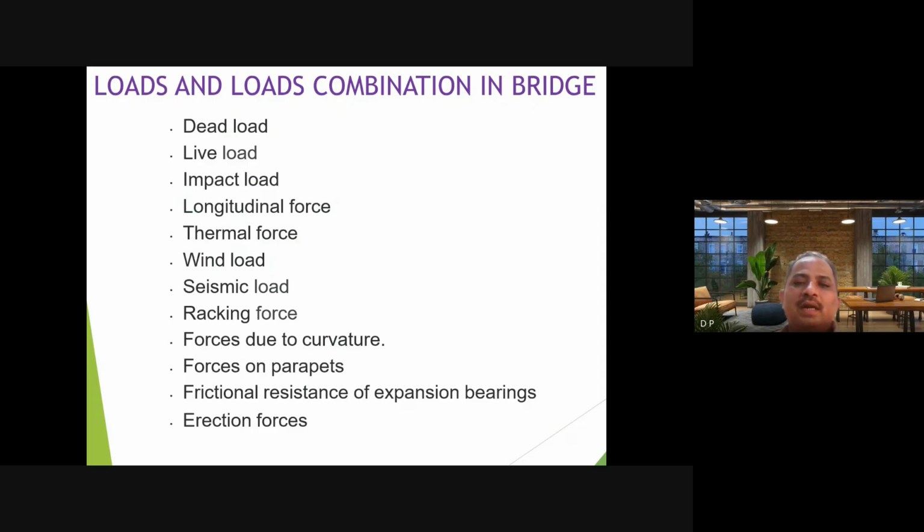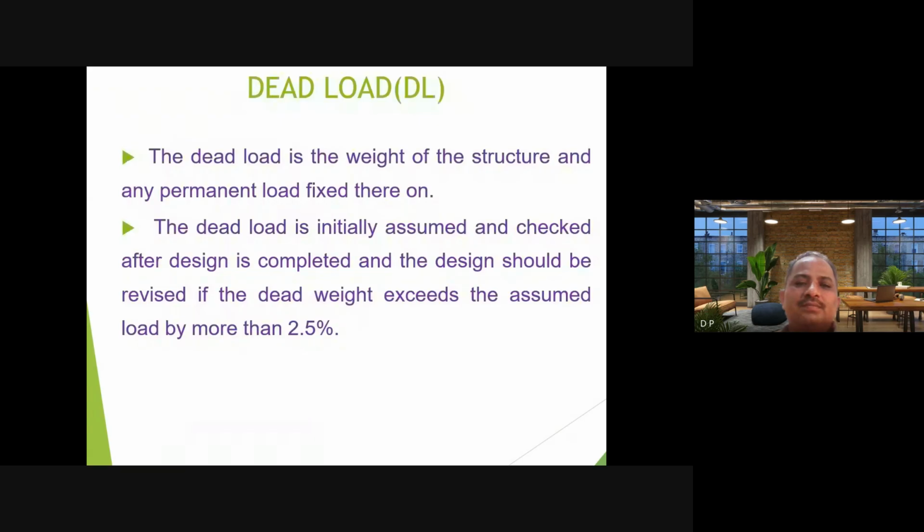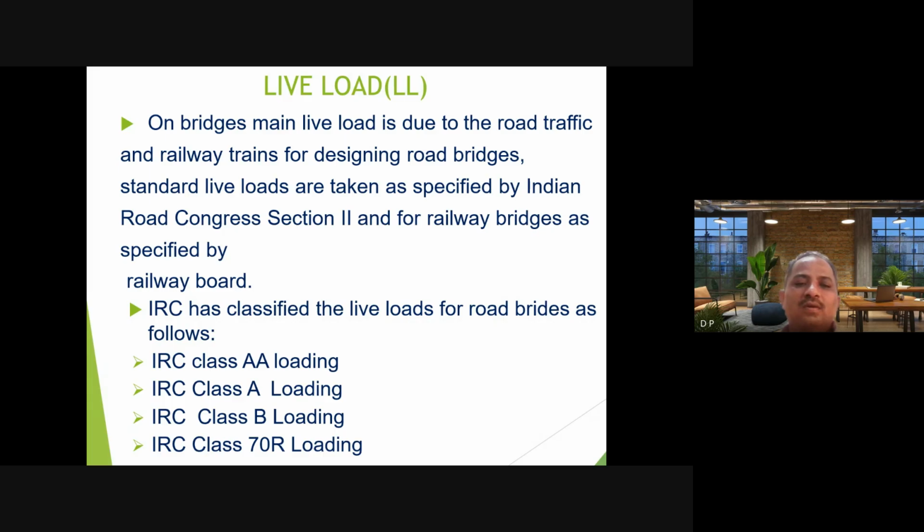Loads and load combinations of the bridge. Dead load: the weight of the structure and any permanent load fixed thereon. Live load: on bridges, the main load is due to road traffic and railway trains. For designing road bridges, standard live loads are taken as specified by the Indian Road Congress.